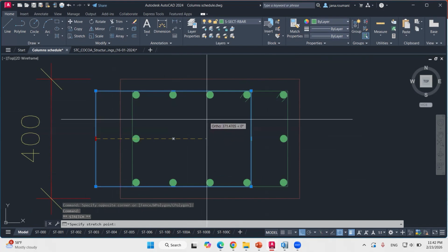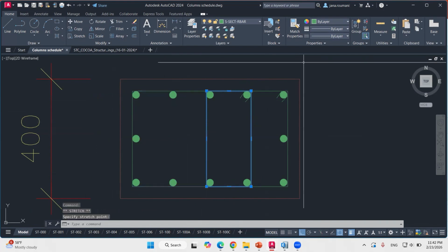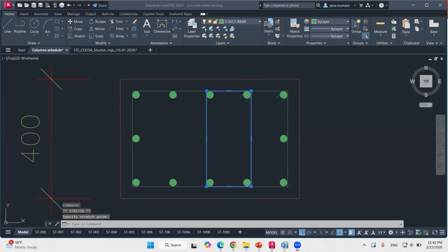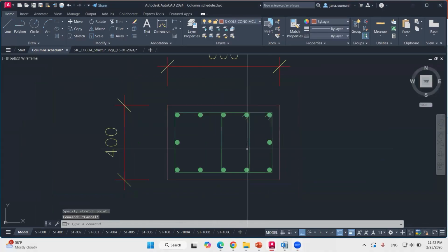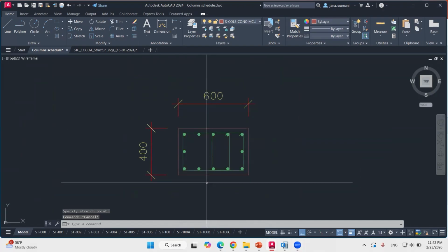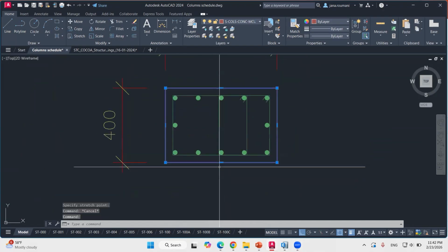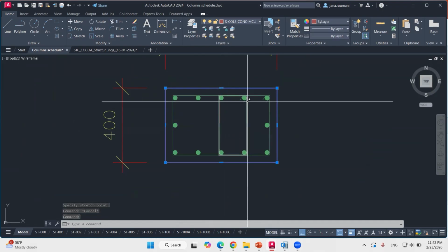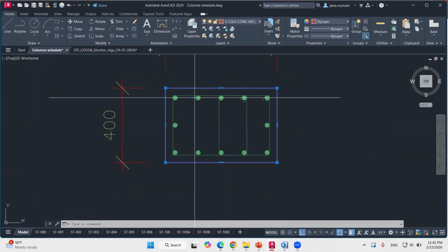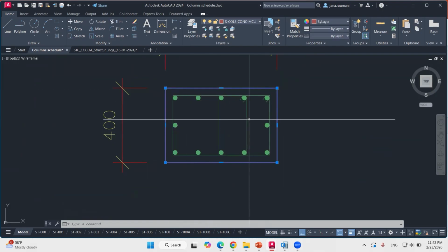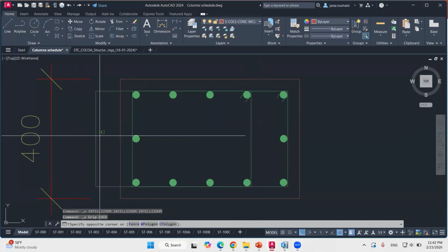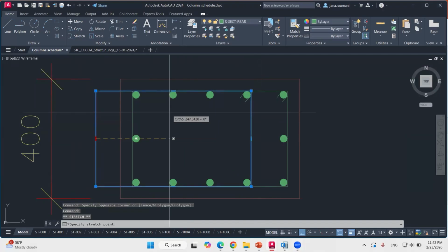And also, I cannot do this, on a side note, because the reinforcement in a column needs to be symmetrical with respect to its center. Okay, so if we consider this column, the center is here. So here we have a tie, but here we don't have a tie. So the confinement should be symmetrical. So it's better to do it this way.